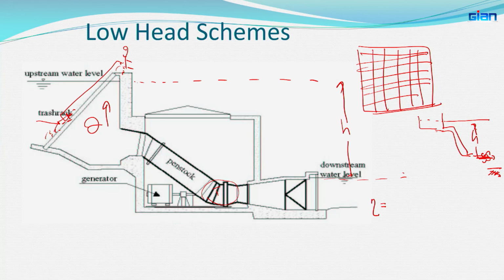Here you can see, efficiency in hydropower plants has many components. So, I would say efficiency is involved wherever energy losses are there, right. The first energy loss will be in the penstock because of the friction and also due to bends, and there will be any other turbulences in the valves, etc.